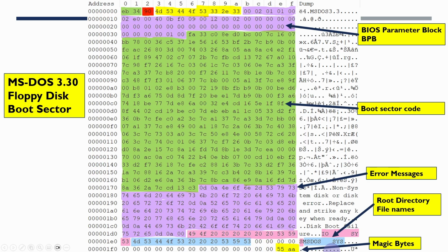So now what I'm going to do is to go into the original Breadboard PC version 1. I've actually put the various logic analyzers on the data bus, the address bus, on the floppy disk controller pins, and also the power on self-test port. So what I'm going to do now is to fire that up. I'll record the logic analyzer signals and we'll have a look at what a correctly operating MS-DOS system looks like when it accesses the floppy disks.